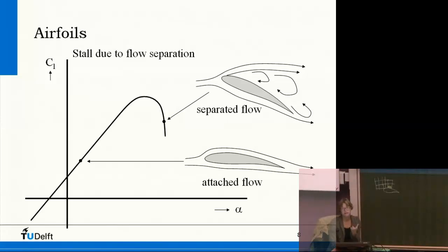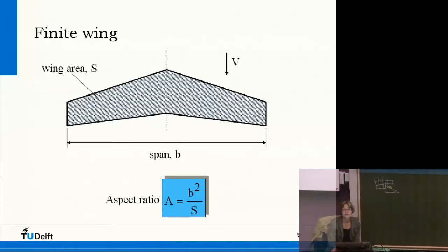So what is typically done is we model it. We model the turbulent scales, because those are the fine scales. These models are tuned experimentally on flat plates and everything, and they're typically bad in predicting separated flow. So this is quite a challenge, a very important part of aerodynamics. Well, this is for an infinite wing.